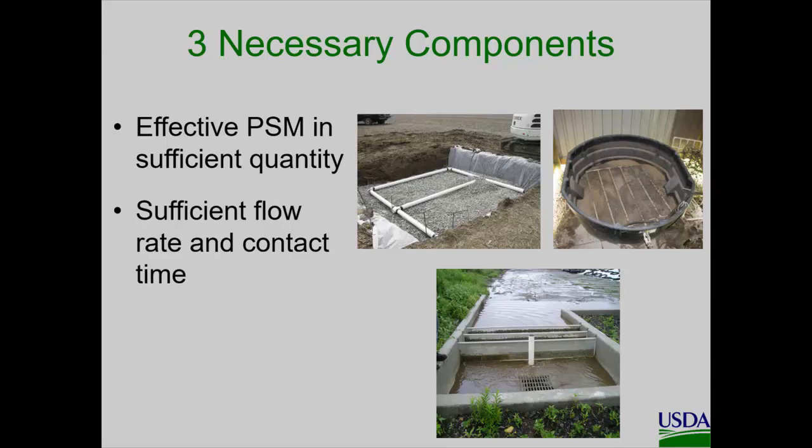All right. Second thing is you have to force water through that filter media at a sufficient flow rate and contact time. Right. The water has to flow through it. If you can't force the water through it, if the water bypasses it or just goes over the top of it, you're not really treating the water. You're not removing it. So it's very important to design these to be able to handle an appreciable flow rate for your site. So like I said, in theory, these work.